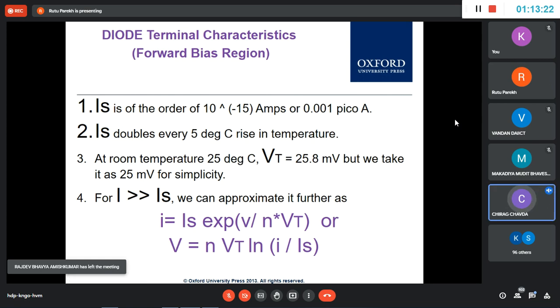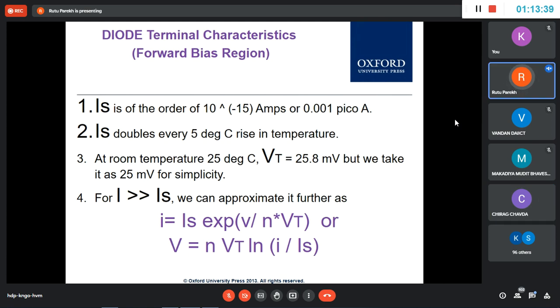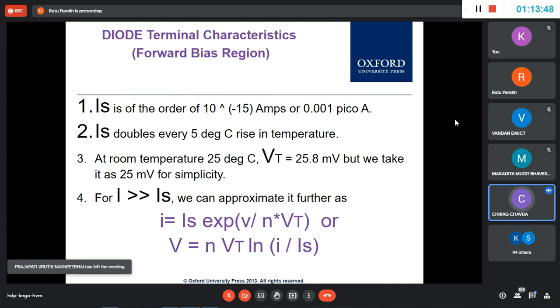So, ma'am, one idea spiked in my mind that we can make one such device using this equation that determines temperature wherever a diode is present. The point is, we can make it a temperature sensor, right? Yes, ma'am. Using this equation, we can have V1, V2, and I1, I2. So we can determine VT, and after that we have the Boltzmann constant and Q, which is the charge.